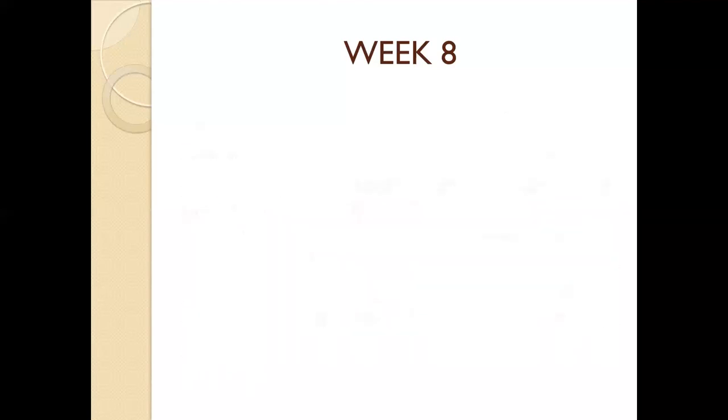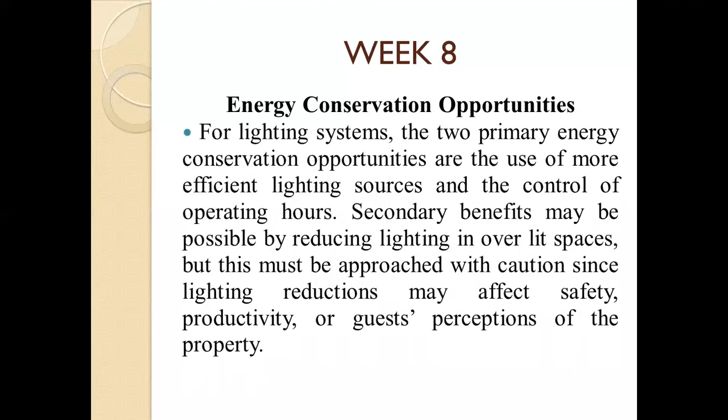Basically, one way to achieve more efficient lighting is to replace incandescent lamps with fluorescent lamps in as many locations or areas as possible. Compact or screw-in fluorescent lamps are available that can be substituted for incandescent lamps in downlights, table lamps, and ceiling-mounted lighting fixtures of various designs. The result will be a reduction of up to 75% in the electricity consumed by the lamp. In addition, there will be substantial labor savings due to the longer life of the fluorescent lamps.